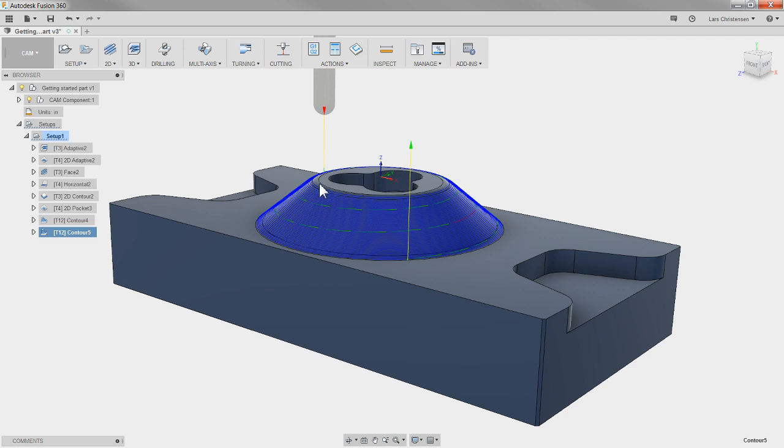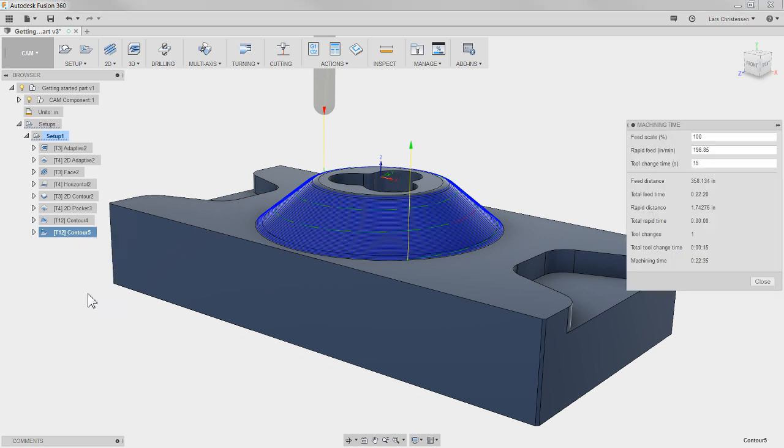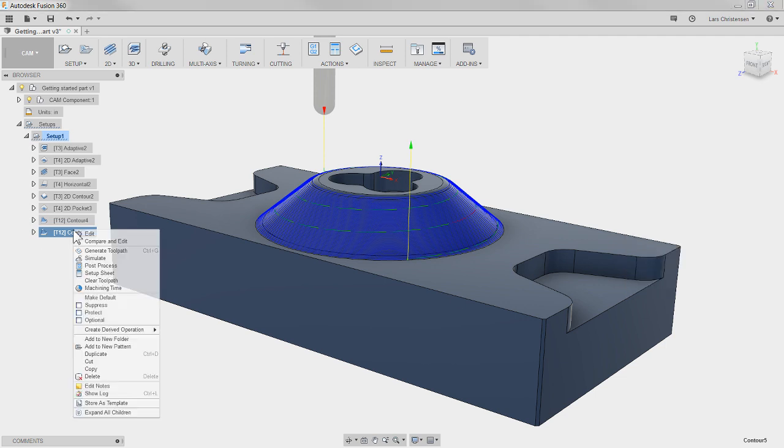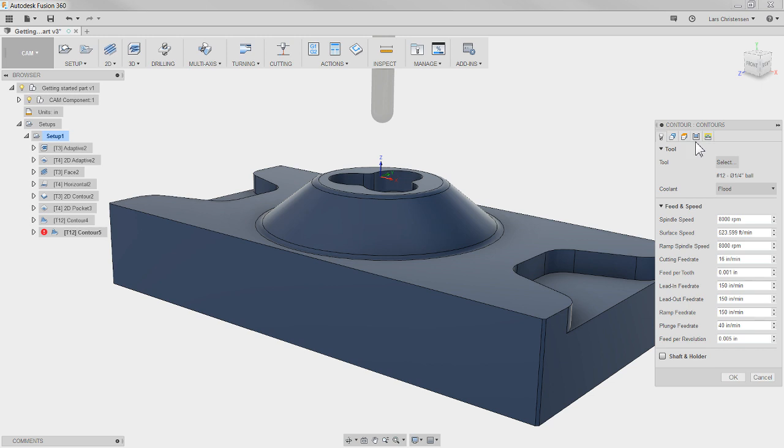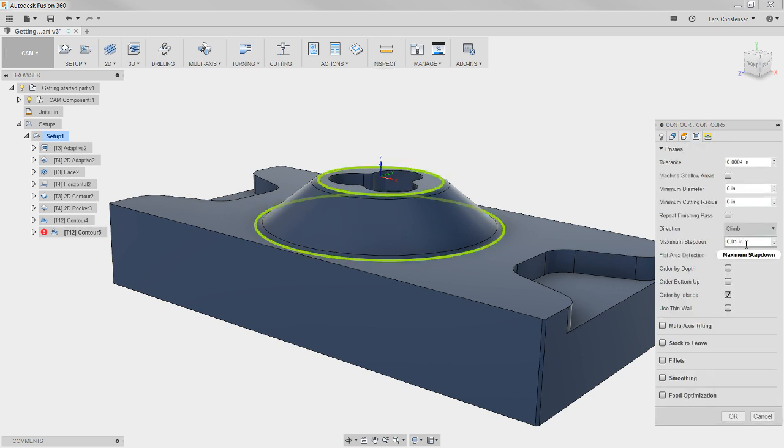And then the boss would come over and say, oh, you need to make it a lot finer than that. It's got to be a lot nicer. And if we go in and look at the time, at 10,000s, it takes 22 minutes. Well, if I have to make it a lot nicer, let's go in here and change this from 10,000s to 1,000s. Now, for some of you European guys, I don't expect you to know what 1,000s is. 3 thousandths is about the thickness of a human hair. So this is like a human hair split in about 3 pieces.